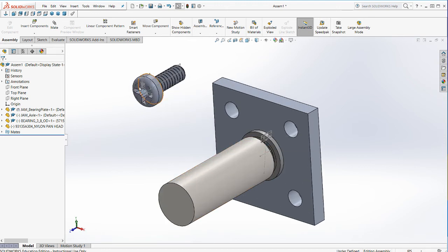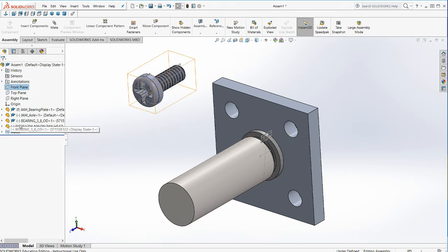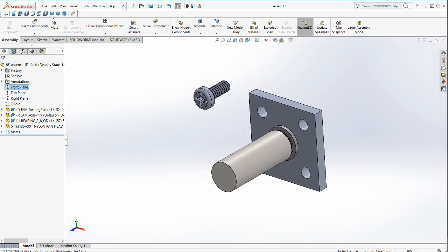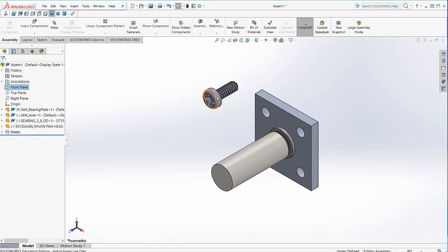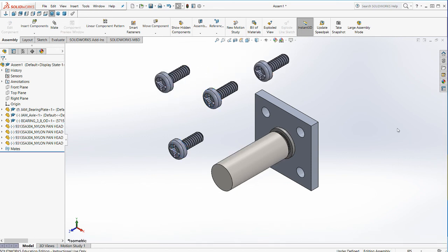Notice that I've got some sketches turned on in the parts that I downloaded. I could go through and figure out what sketches are on. I can also just change the visibility to turn off the visibility of sketches. Something that I find a really useful setting. And FYI, shortcut, and this will be the last thing I think I show you right now in your assemblies. If I select a part and I wanted more of them, if I hold down the control key and drag it, it automatically duplicates that part. Nice little shortcut that makes things like hardware a little bit easier to work with.